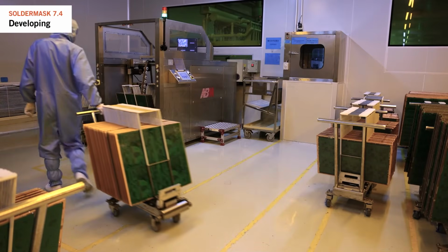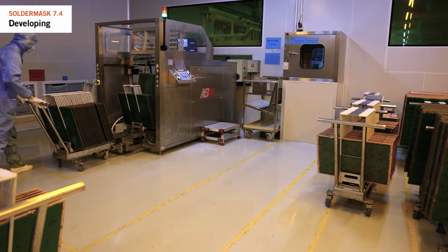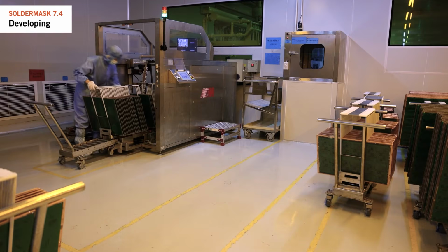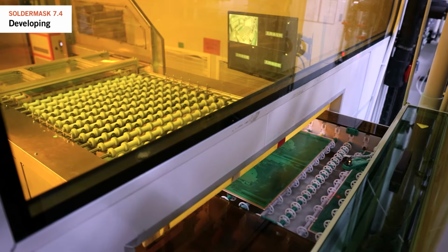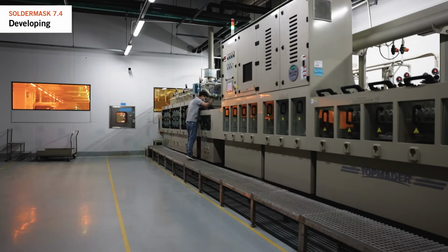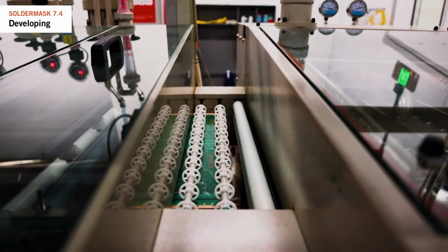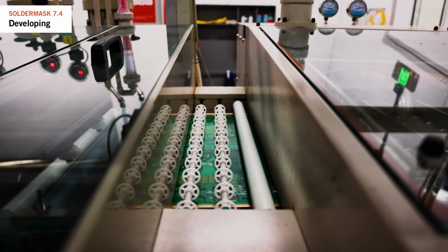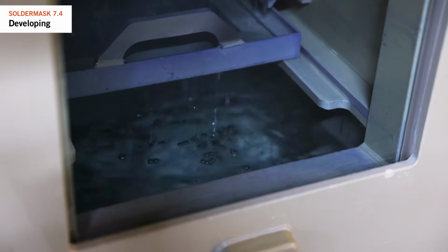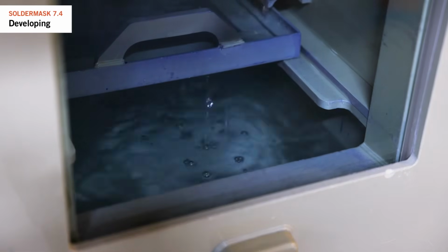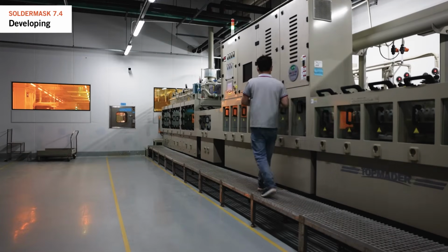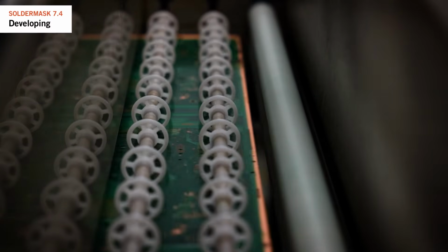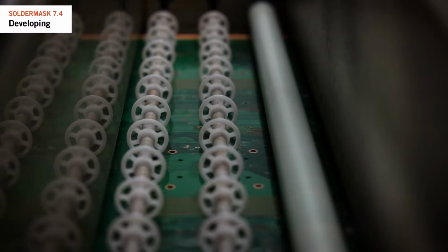After solder mask exposure, we can remove areas with unwanted solder mask through a development process. The production panels are placed in a developing line where chemicals are sprayed onto the solder mask layer from both sides. The unexposed solder mask areas are not resistant to the developing chemicals and are effectively washed off. The areas with exposed polymerized solder mask are resistant against the development chemicals and remain on the PCB surface.